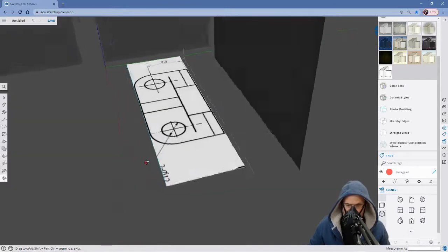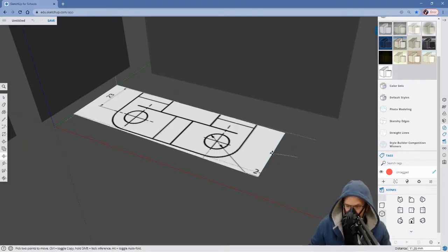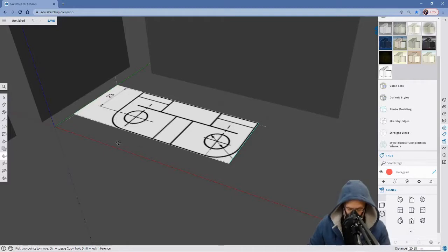Now, I'm going to do the same thing on the sides. Bring up my pointer, select the edge. Notice it turns a vibrant green. Choose the move tool now. Slowly, notice it's following along the red axis. Move to the edge. Pointer tool.